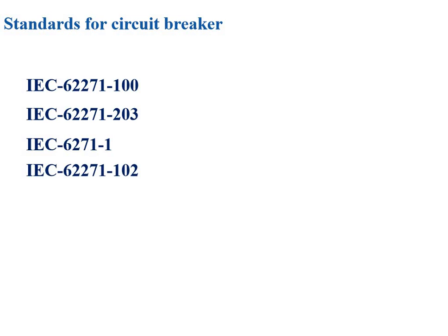The next is IEC 62271-102, which is used for the alternating current earthing switches. It is also used for the induced current switching. The next IEC standard, 60137, is used for the bushing for alternating voltages above 1000 volt. The next is IEC 62271-209. This standard is used for the cable connections for gas insulated switchgear.